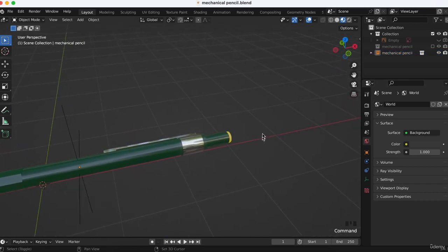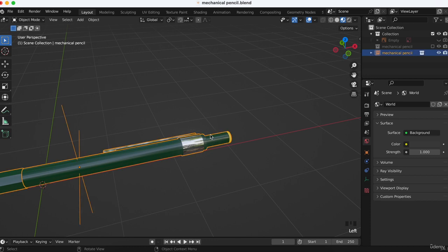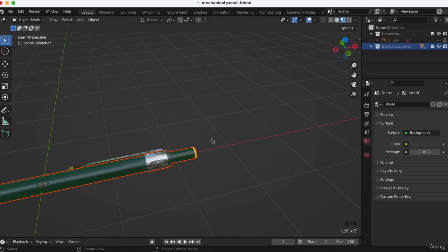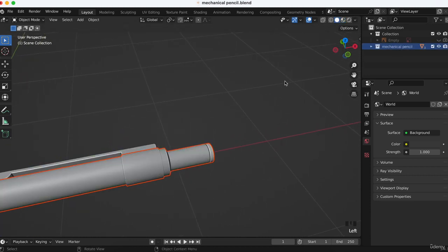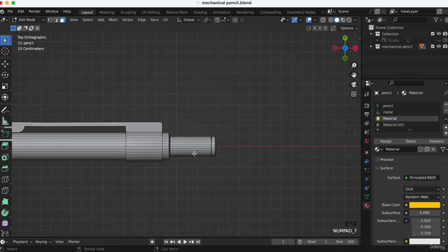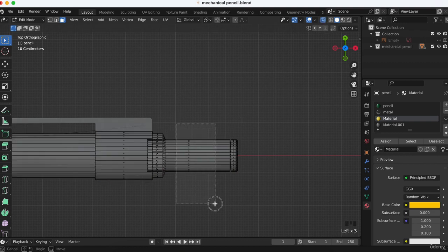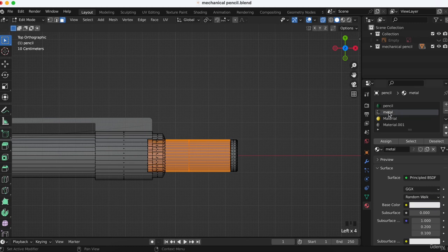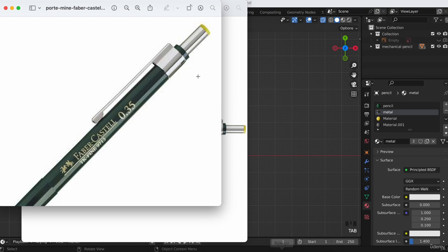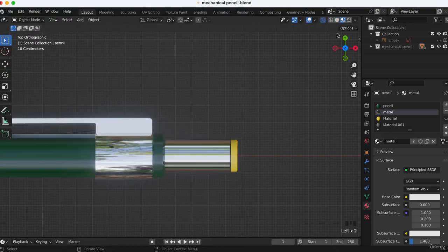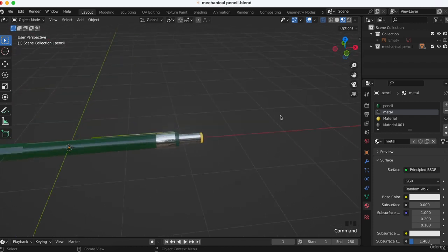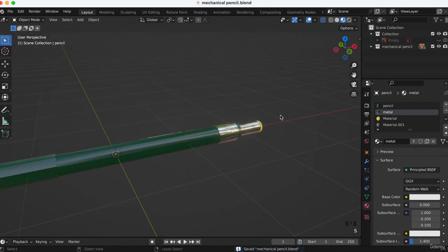And also I forgot to put this part metallic. We can delete this X, put this part back, go on solid, tab to go on edit mode, numpad 7, and then on X-ray here, get these faces, and then put just metal here, assign, and it's gonna be good. We can go back here in the material preview, and now everything is good and we can save.